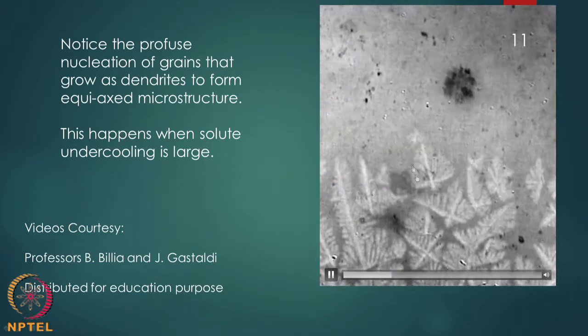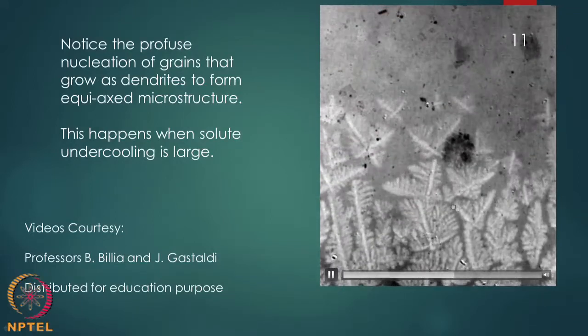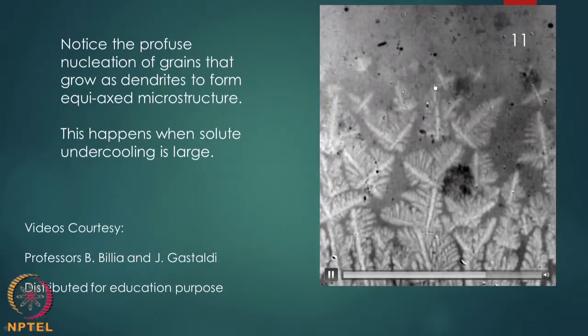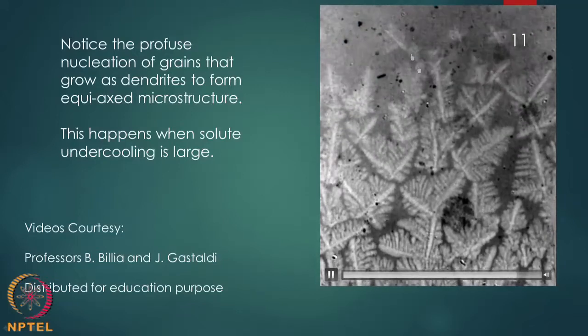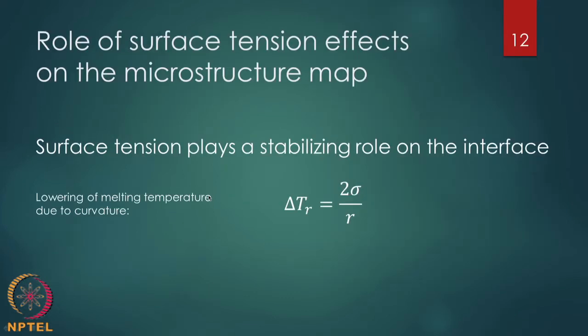And as you can see, the grain boundary around these dendrites is going to give you a much smaller grain as compared to a long dendritic growth. So, these grain sizes are generally small and also good for the impact toughness of the weld, which solidifies in this kind of a mode. So, at this juncture, let me then come back to the analysis.